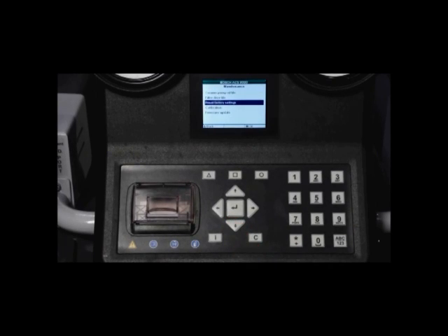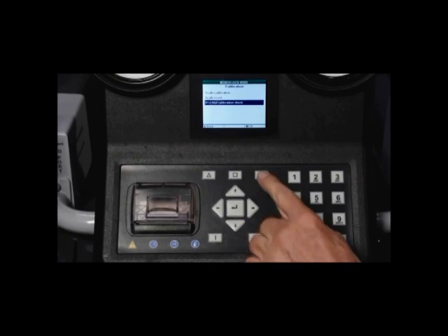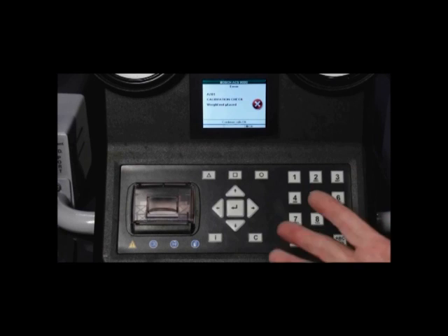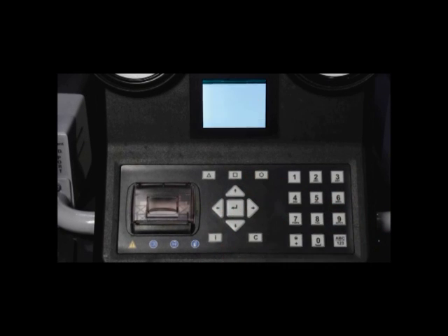I am not going to go to factory reset because the parameters are already set. Go to calibration, scale calibration, scale reset, calibration check. I'm going to go to calibration check. It tells me to do the calibration check and tells me to put the ball, just like we did with the 980. Continue with OK. Okay. Put the weight on there. Since I didn't put the weight on there, it failed. Update. Since we don't have any update software right now, there's nothing to do.